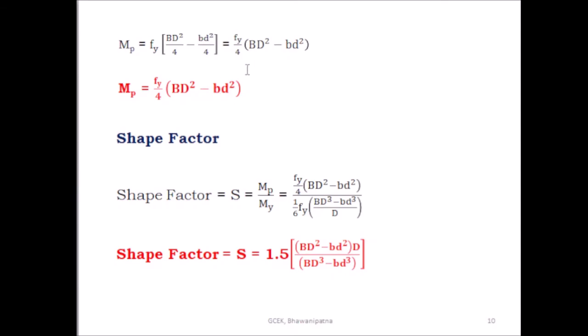Then after getting the yield moment and plastic moment, you can find out the shape factor. The shape factor is equal to plastic moment capacity by yield moment capacity.